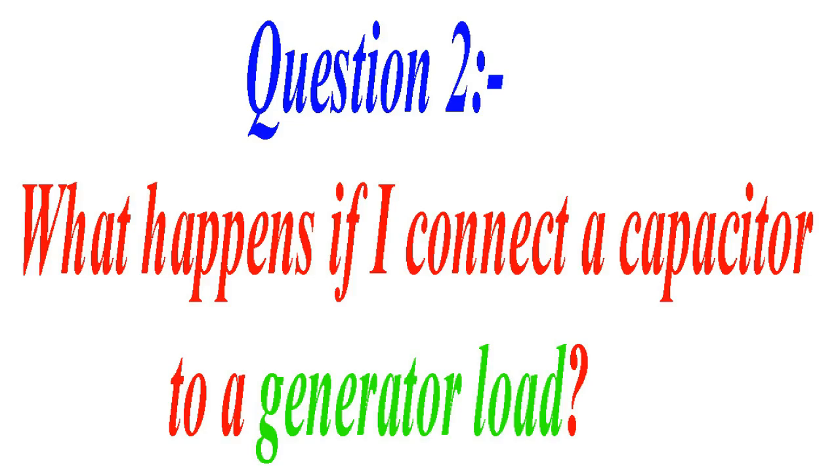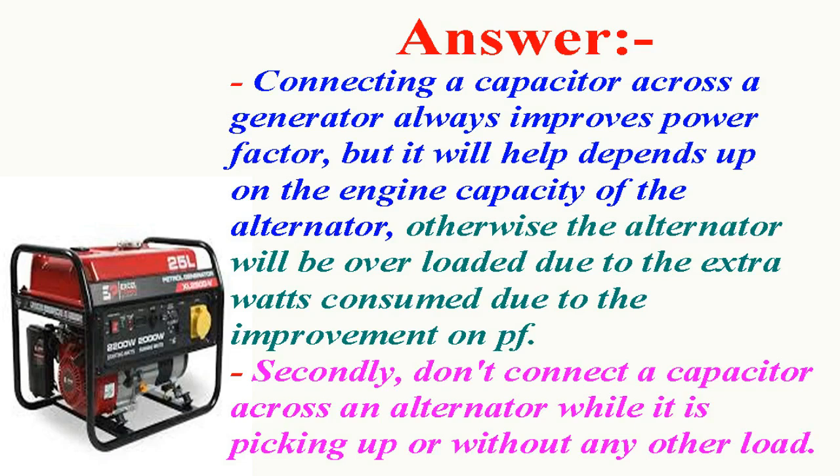What happens if I connect a capacitor to a generator load? Connecting a capacitor across a generator always improves power factor, but it will depend upon the engine capacity of the alternator. Otherwise, the alternator will be overloaded due to the extra watts consumed due to the improvement in power factor. Secondly, don't connect a capacitor across an alternator while it is picking up or without any load.